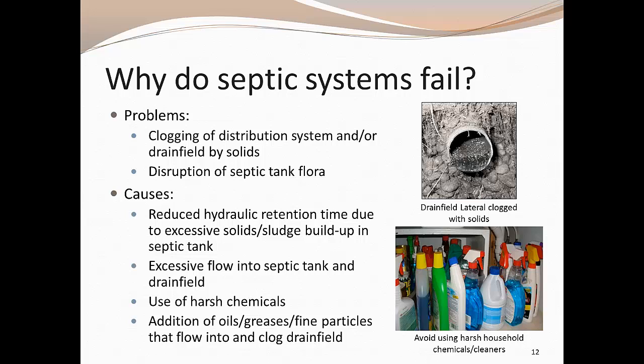Look for septic-safe alternatives. Another cause of failure is that related to the soil treatment area clogging: excess water use in the home. When too much water enters the tank too often, the solids don't have the opportunity to settle out, and the sludge in the tank can be resuspended. To the extent possible, spread out heavy water use over time. For example, avoid doing multiple loads of laundry on any one day.